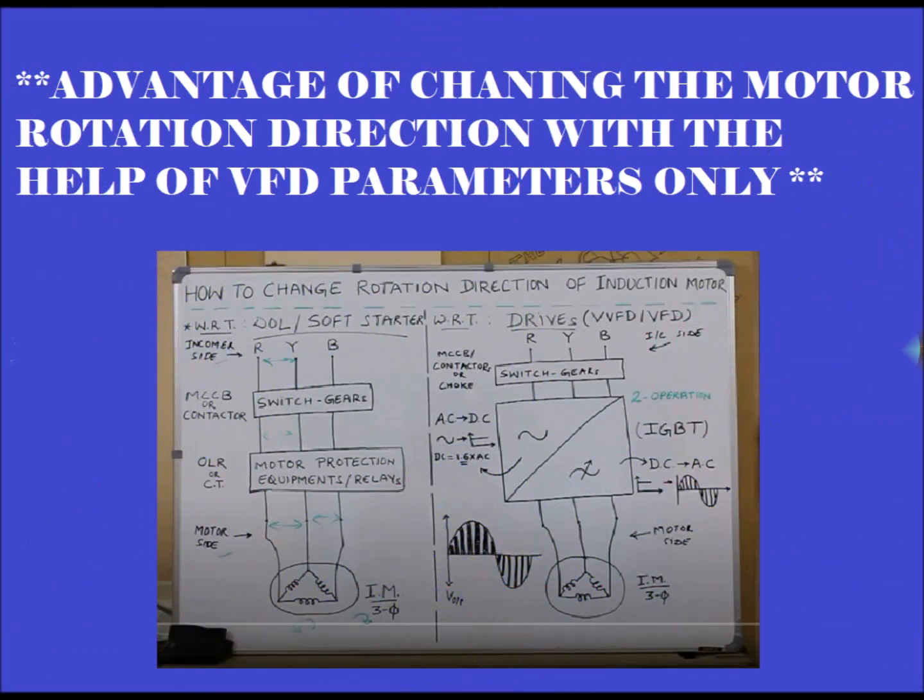One important advantage of using a drive is that we can change the direction with the help of a parameter itself, but in case of any other starter you have to make physical changes to the cable. There is a separate video on this, you can find the link in the description.